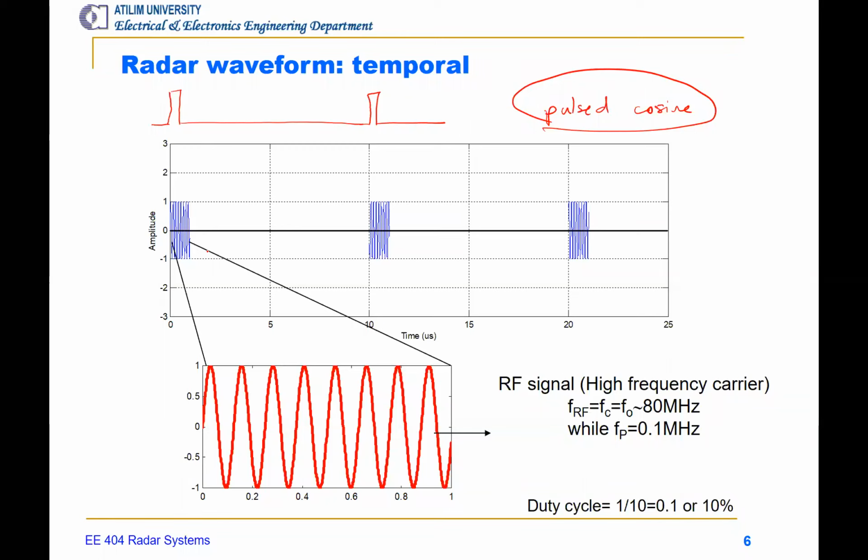So then we can illustrate again a more realistic radar waveform. Then we have one more parameter here, which is the frequency of the cosinusoid. We know the amplitude of this cosinusoid, which is PT, if this axis represents power, the peak power. Now we have to define the frequency and then the period of this carrier.